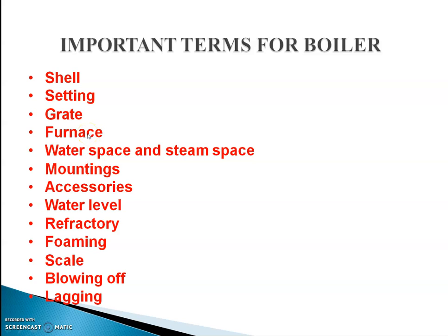The furnace is a closed chamber formed by the space above the grate, below the boiler shell, in which the combustion takes place. It is also called the fire box. Water space and steam space: the volume of the shell that is occupied by the water is termed water space, while the entire shell volume less the water and tubes is called steam space.